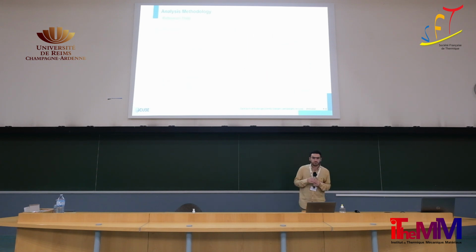Finally, in the methodology, I'm going to talk about the reference state, because if you have noticed in the equations of exergy, we have to choose a reference state where the system equilibrates with. So this reference state is usually the environment around the system, and it is the environment that the system interacts with without this environment losing its intensive properties. In the case of an air heat exchanger, it is sufficient to talk about a restricted dead state or restricted reference state, where we don't take into account the chemical interactions with the environment. And this is valid in our case because we don't really have chemical interactions between the system and the soil or the air around it.